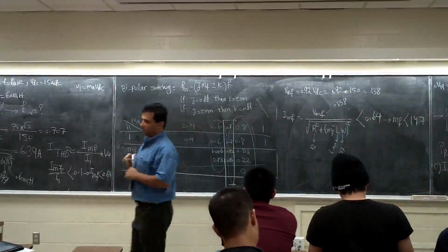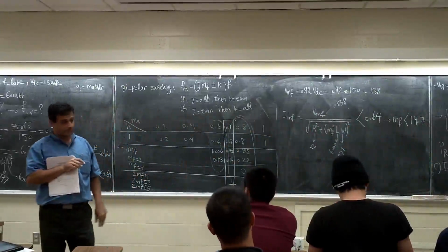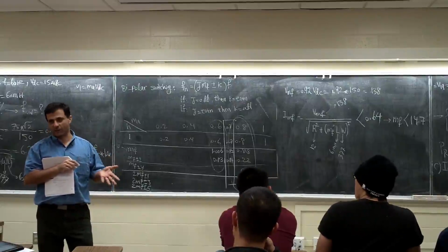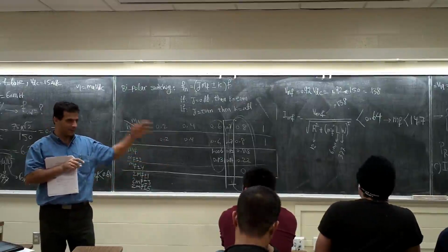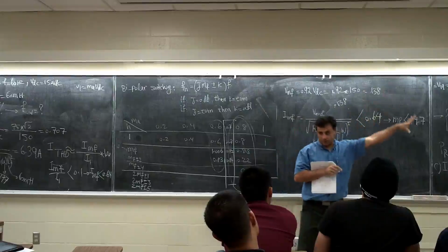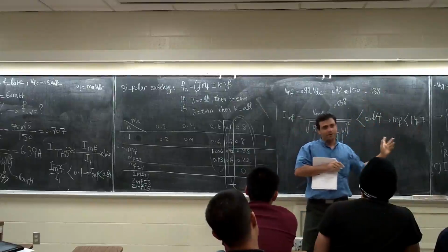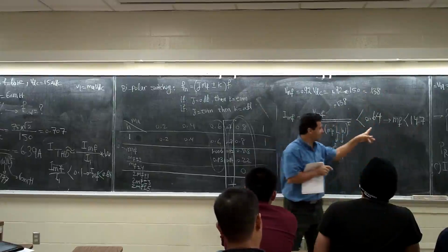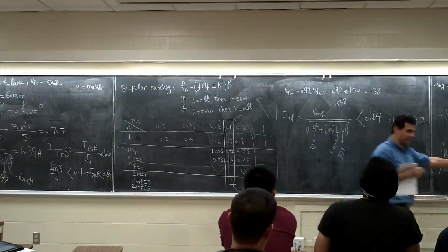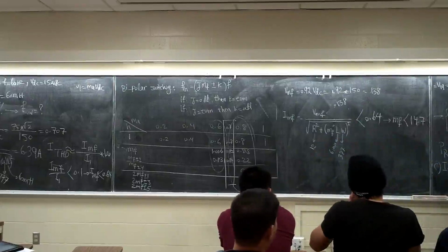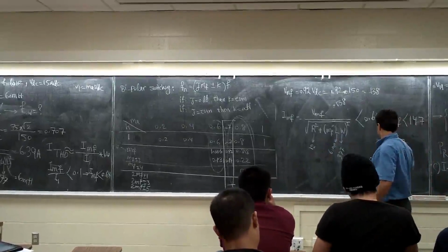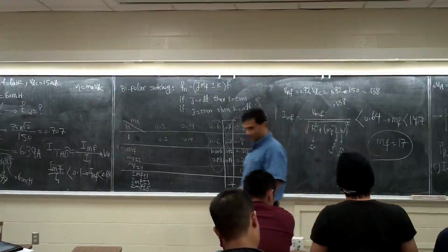So, what number do you select? A little bit higher. That's lower. First of all, it must be an integer number. We cannot have an MF of 14.7, right? So, what's the next integer number? 15. Remember, the higher the switching frequency, the better for THD, right? 15, but very close to 14.7, a little bit more than that. I had all this assumption here that I didn't count, right? Let's go with MF 17 to make sure we are clear.